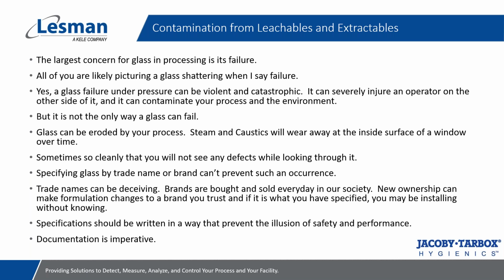So glass in these processes can be eroded from inside, and it can happen so cleanly that you won't even see it happen. We've actually had windows that were taken out of service and showed to us that were made of soda lime glass, and half of the thickness of the glass was eroded from the inside, and it showed no visible defects from the outside.